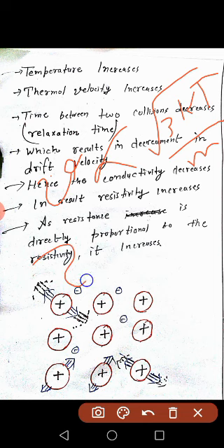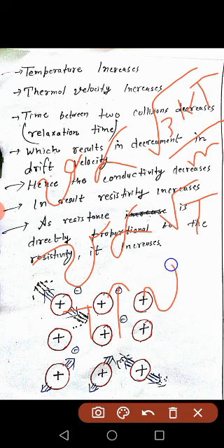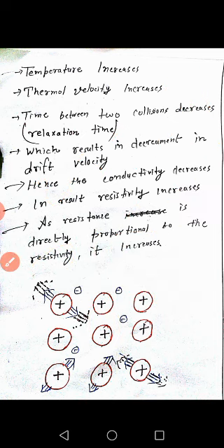So here we can conclude velocity is proportional to the square root of T. So if the temperature increases, that velocity also increases, which is the thermal velocity. In the terminology related to the kinetic theory of solids, that velocity is also called the RMS velocity of the electrons. Okay, so the first point is clear. The thermal velocity increases whenever we increase the temperature.